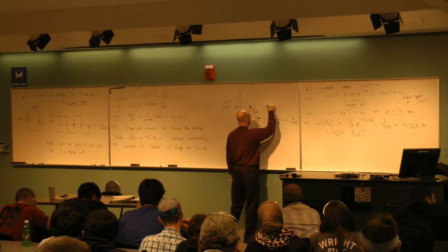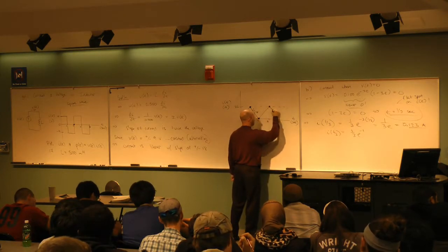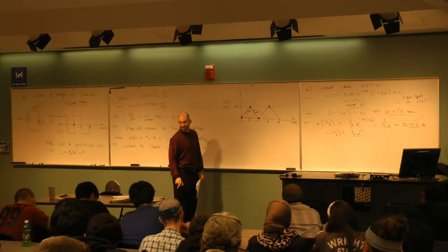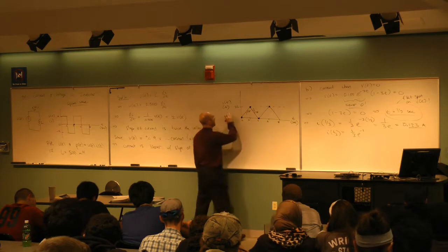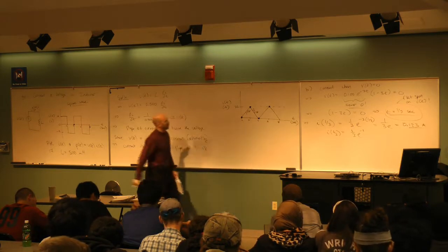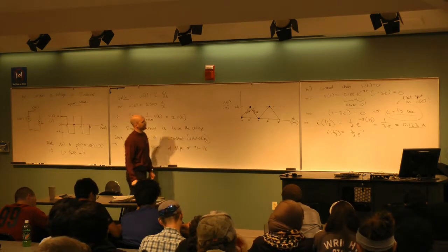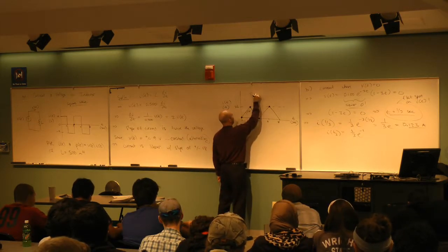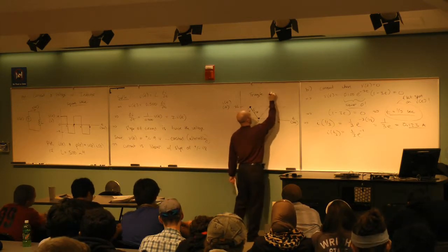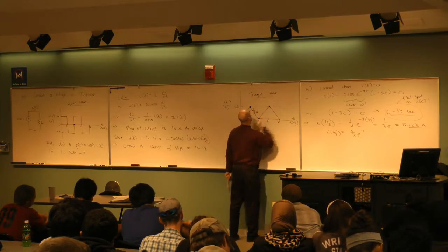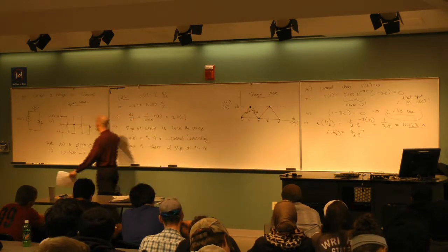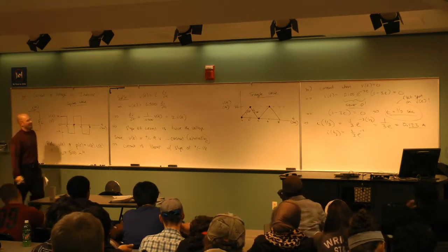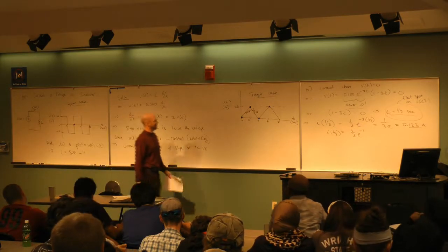So apparently then, if I apply a square wave to a voltage across an inductor, then I of t, what kind of wave would we call that? Is that a sawtooth? Yeah, I'd call this one a triangle wave. Okay, so I start with the square wave for voltage. This is if I have an inductor. That gives me a triangle wave for the current.